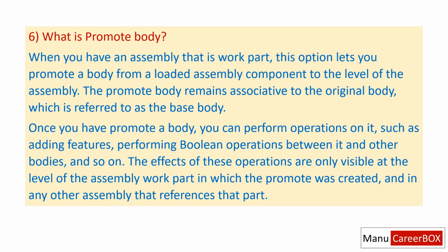6. What is promote body? When you have an assembly that is work part, this option lets you promote a body from a loaded assembly component to the level of the assembly. The promoted body remains associative to the original body, which is referred to as the base body. Once you have promoted a body, you can perform operations on it, such as adding features, performing Boolean operations between it and other bodies, and so on. The effects of these operations are only visible at the level of the assembly work part in which the promotion was created, and in any other assembly that references that part.